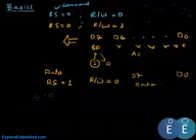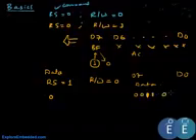So say we want to display number 0. The ASCII value for that would be 30 in hex. That would be 0011 0000. So this is 3 and this is 0, and this would be the data on the data bus. So if you want to display other characters, you need to send the ASCII values.